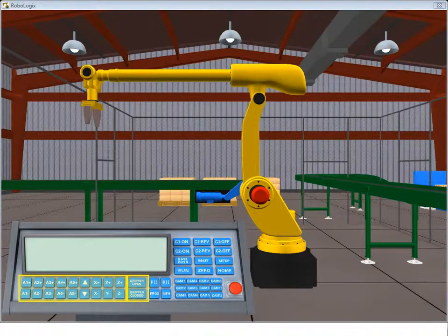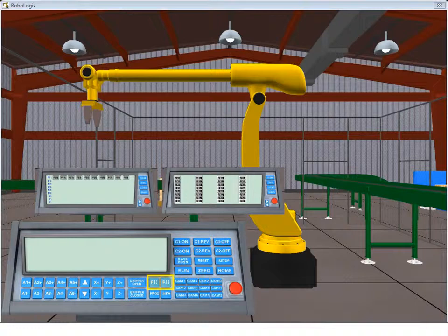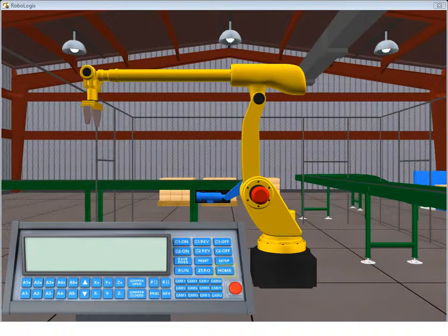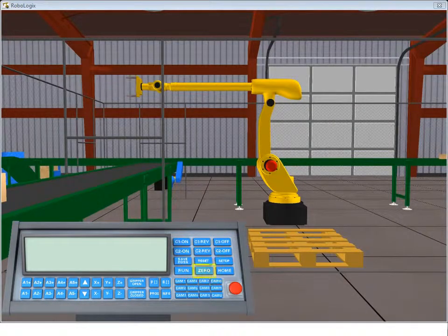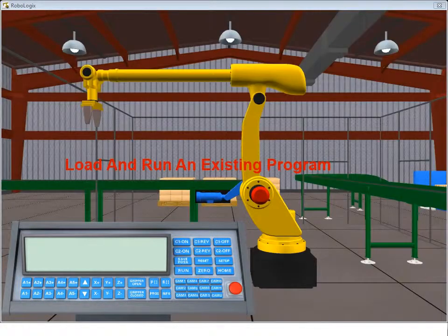Robot motion and gripper controls provide control over the robot for position jogging. By using the jog buttons in combination with the Save Position button, the robot can learn positions and return to them at a user-specified rate of speed. Access to the position and variable registers is also available from the control panel. The Home Position button provides a predefined starting point that can be used as a reference for program execution. The 0 button moves the robot to a location with a 0, 0, 0 reference point as an alternative to the home position.